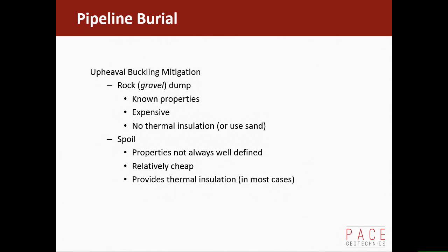Now, we can use the soil from the trench, or spoil if you like. The issues there are the properties aren't well defined. We might have done the best survey in the world before we've laid the pipeline, but that's measured the strength of the seabed soils before they've effectively been pulled out of the trench and then pushed back in. So understanding those properties is a bit of a challenge.